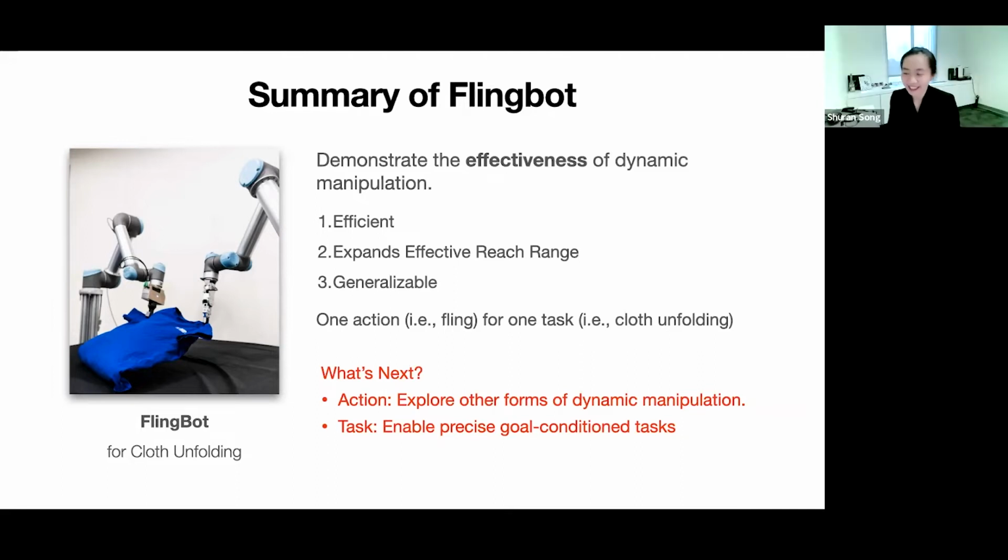Yeah, so actually that's a good question. That's also the part I skipped. We divide the primitive into several stages, but for some of those actions there are very natural solutions. For example, for cloth unfolding, you probably just want to stretch it as far as possible, right? So we use the camera in the front and just ask the arms to stretch as far as possible, and that part is not learned. Similarly, the Fling primitive is also not learned. It's a fixed primitive.